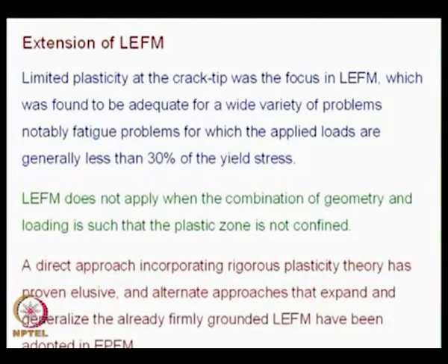So, there is similarity between what you have done in LEFM. There you had fracture toughness K1C has to be determined. Similarly, here you will find out J1C has to be determined. So, there is parallelism in this, but you need to go through certain approximations. So, before we get into elastoplastic fracture mechanics, we will try to understand what is J integral. That is the way that we are going to proceed.